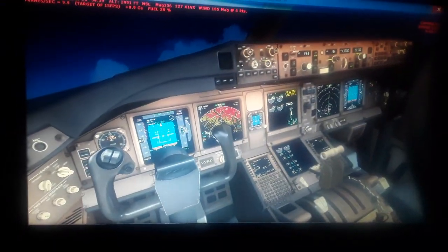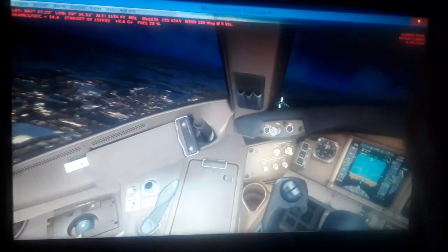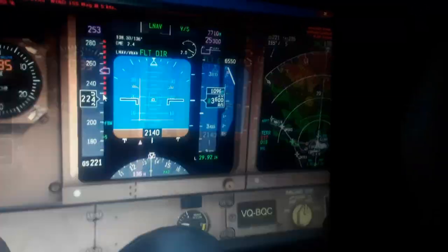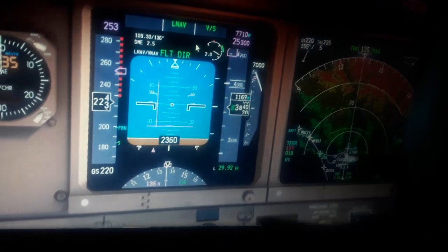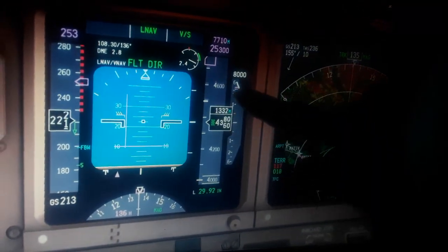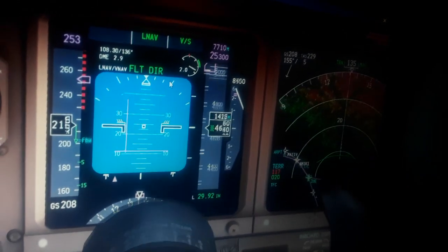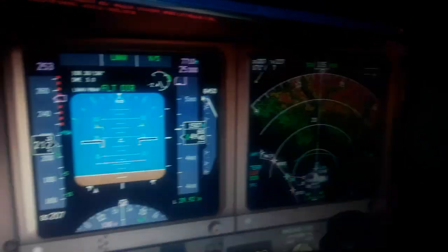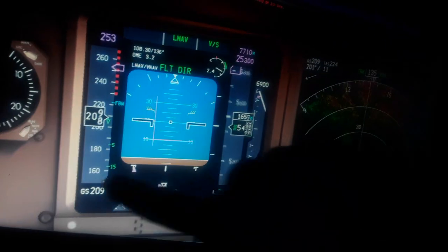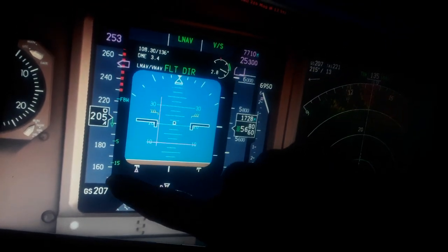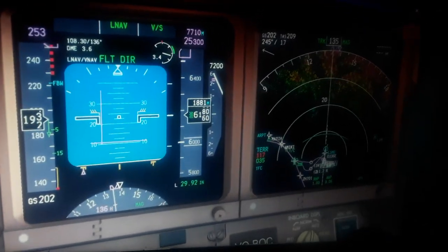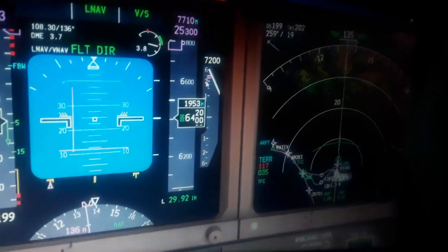Pitch trim a little bit down, not exceeding the pitch ladder. So these are the indications. Now we are 2,200, 2,400 feet above ground level, but 4,000 feet above sea level. Climb at 8,000 feet per minute. You can see the airspeed here, 200 knots, the ground speed, the flaps limit, and also the stall speed 145. The warning is stalling at about 130 knots, 135.